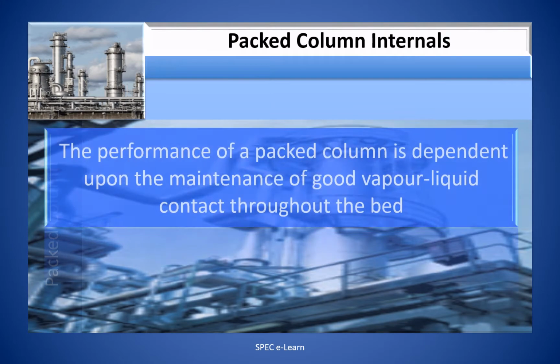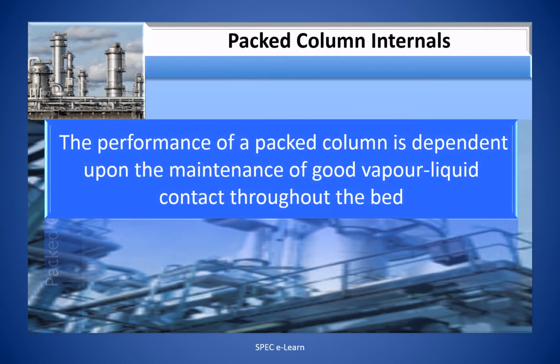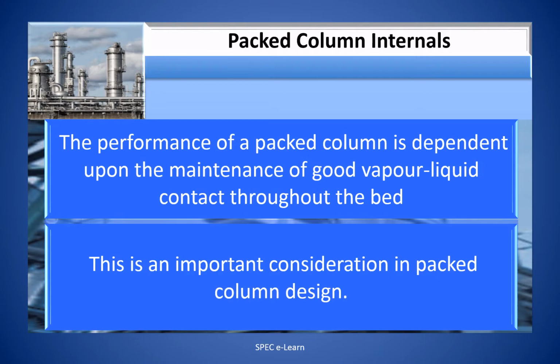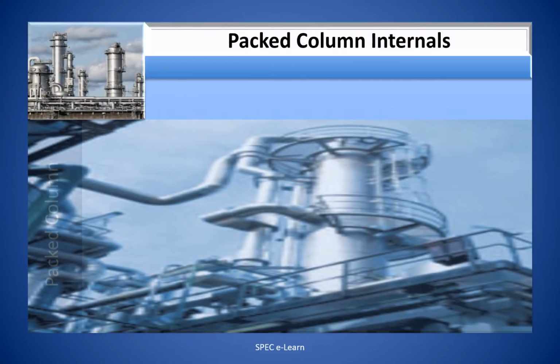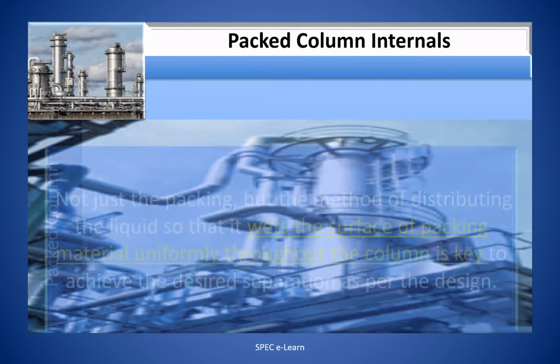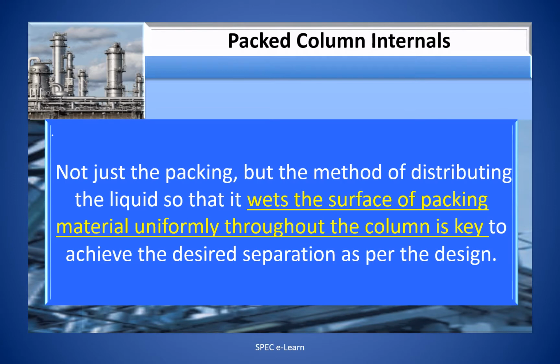The performance of a packed column is dependent upon the maintenance of good vapor-liquid contact throughout the bed. This is an important consideration in packed column design. Not just the packing, but the method of distributing the liquid so that it wets the surface of packing material uniformly throughout the column is key to achieve the desired separation as per the design.